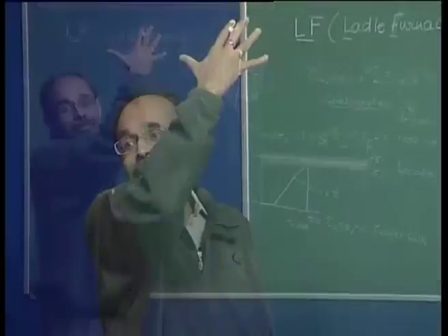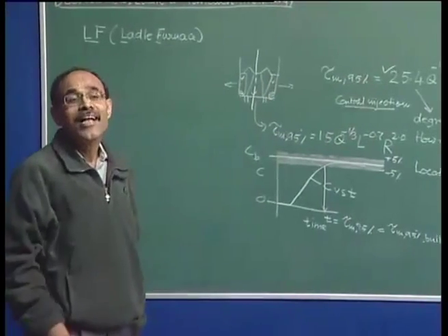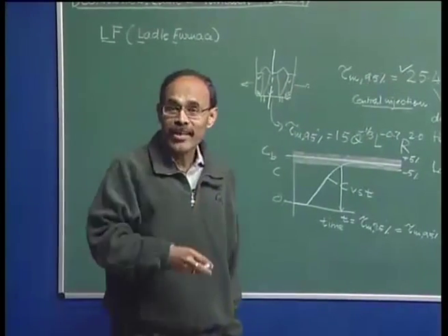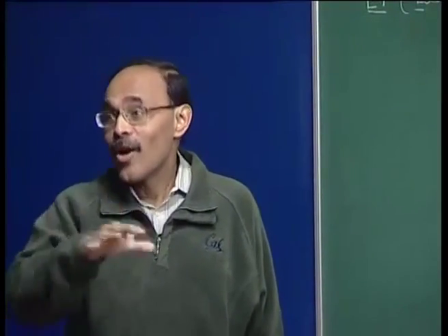It is not desirable that steel from the primary steel making vessel should be tapped at a very high temperature to compensate for this temperature loss or the requirements of secondary steel making. That is a very stupid way of doing things, because the higher the temperature in the primary steel making furnace, the lower the life of the refractories there.